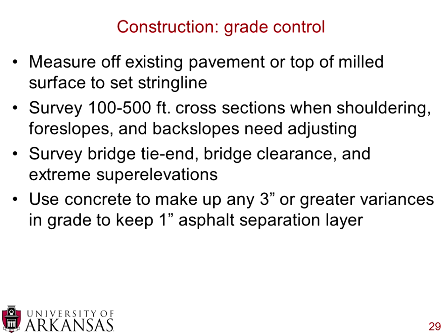You want to make sure that you survey traditional problem areas, which could be bridge tie-ins, any sort of bridge clearance, and also extreme superelevations. So areas where you have unique situations, you want to make sure you survey those areas. And then finally, you also have the ability to use concrete to make up any 3-inch or greater variances in grade.